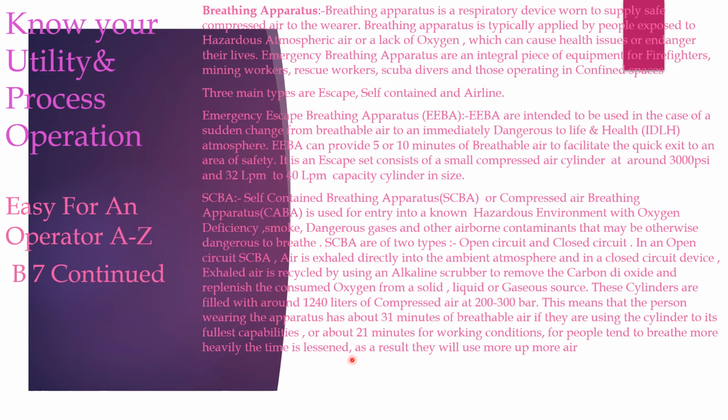The time is less, as a result, they will use more air. So SCBA can be used a minimum of 21 minutes and a maximum of 31 minutes based on their capacity, and also based on the working condition. You can see other important details in the next slide regarding the breathing apparatus.